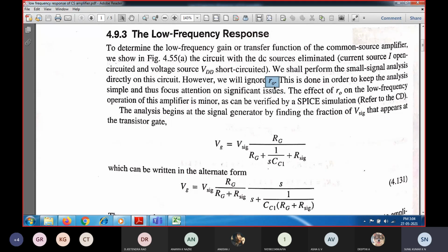So we will have one VGS term, and a constant current source gm times VGS, and that device is going to have three terminals: gate, source and drain. So between gate and source you're going to have an open circuit. So there will be no resistance associated between the gate and source, it is infinite resistance. Because of which we are going to have VGS as the voltage.